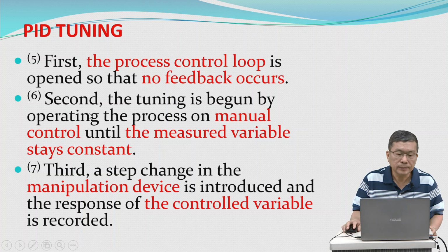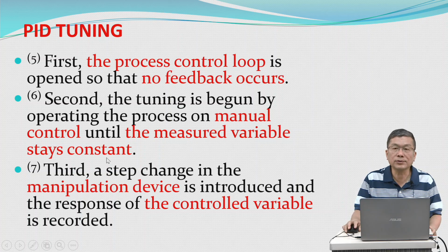Second, the tuning is begun by operating the process on manual control until the major variable stays constant.